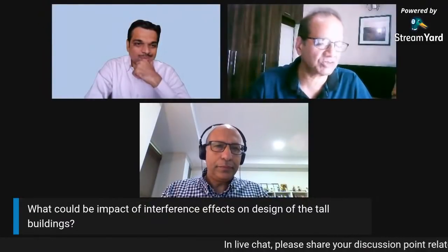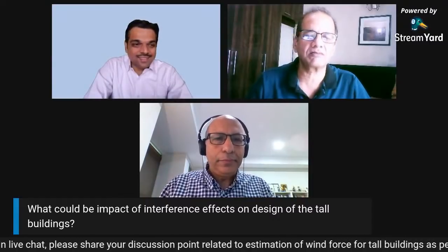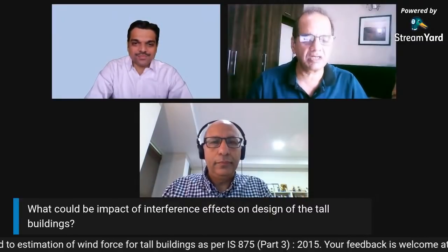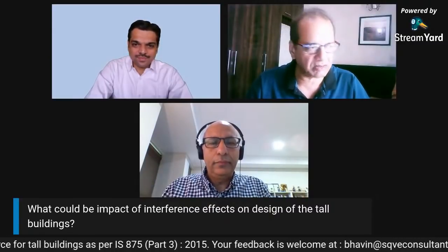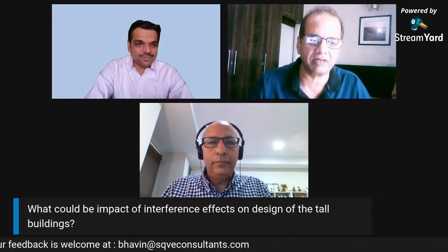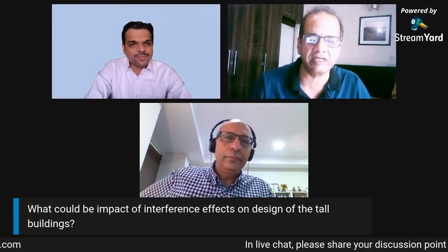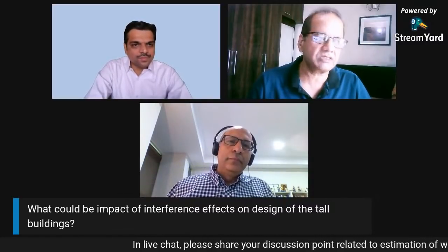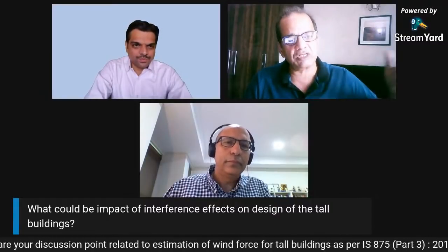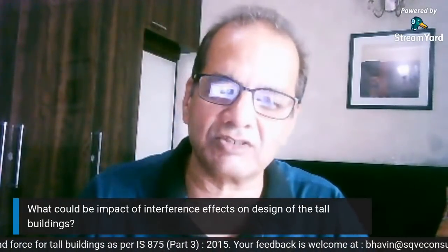Yes, it's a very exhaustive subject, and as such, no theoretical formulation is there. But certainly, there is an adequate number of experiments done on models, and even full-scale measurements have shown that there is a significant impact of interference on along wind as well as across wind. There are certain situations where shielding is also there. Interference is not always due to the building which is upstream. If a building is constructed downstream, then too there is an interference effect on the upstream building which is already existing.